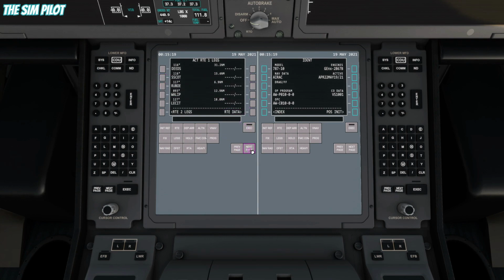No discontinuities on this page, and on this page there is a discontinuity because of a vector. To clean this, you need to delete the vector. To do that, you select delete and then hit the vectors. Execute. When you delete that, the discontinuity is automatically cleared.